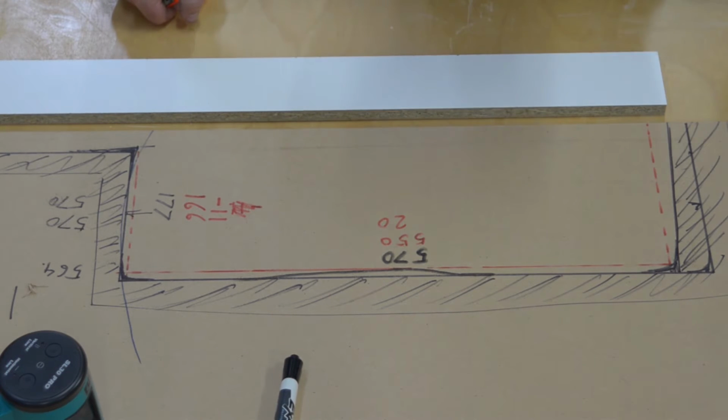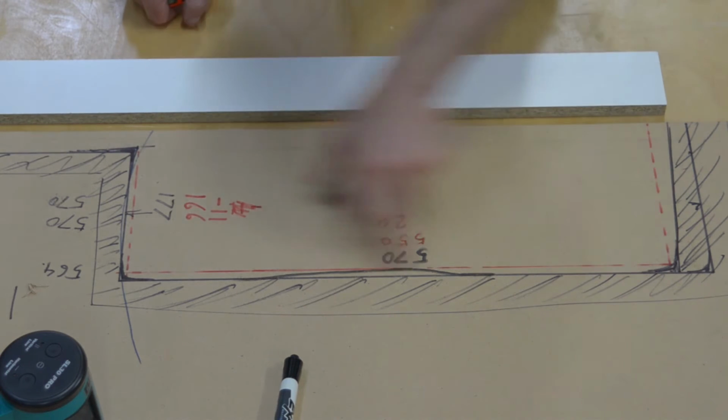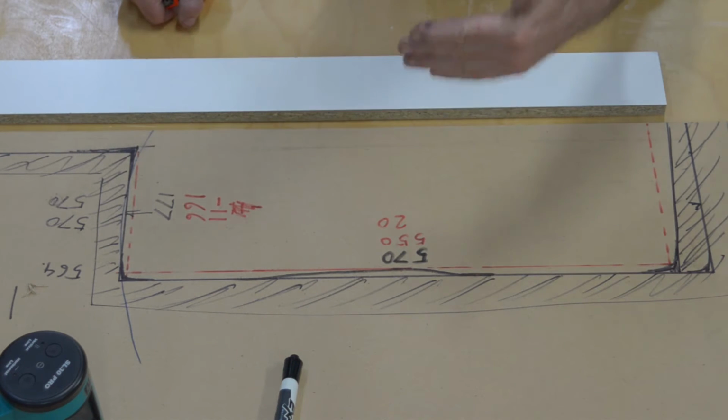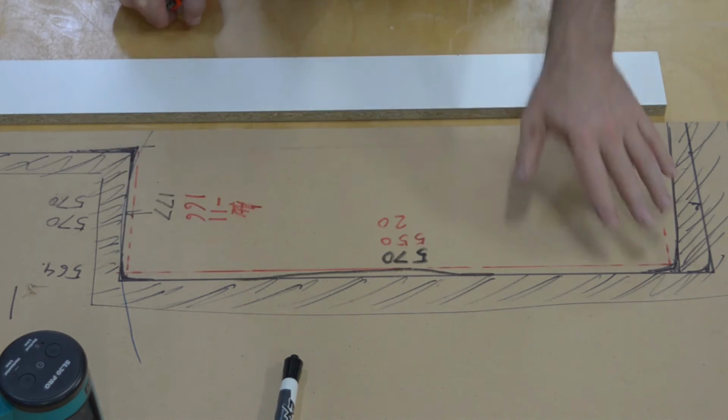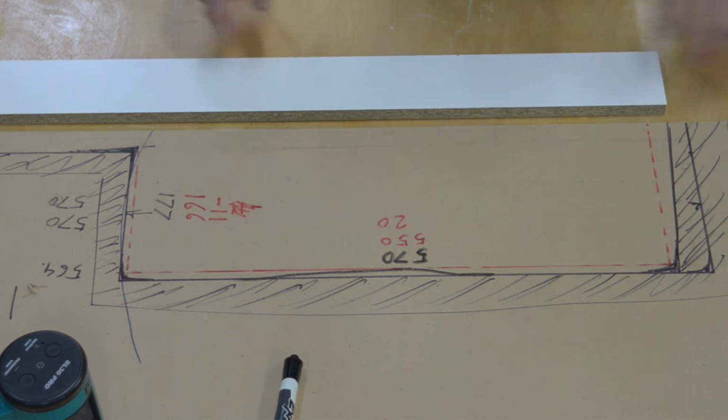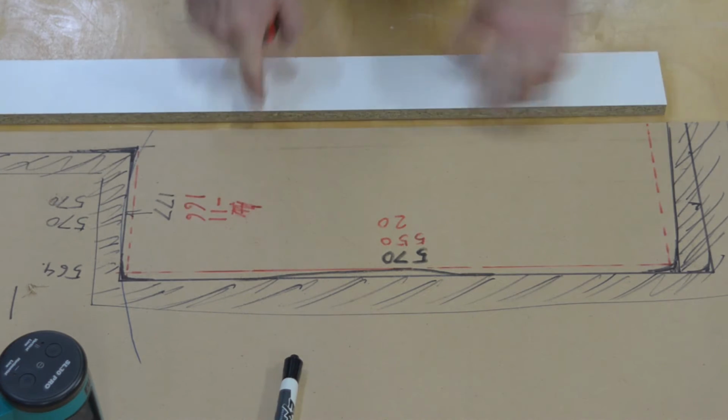The walls will also not be plumb. You can use the spirit level to measure how plumb the walls are, but basically the conditions are the same as going across. There'll be all sorts of reasons for the verticals to vary as much as the horizontals vary. So it's worthwhile keeping an eye out for any of those deviations you see. Okay, so that's one way of establishing a straight line.